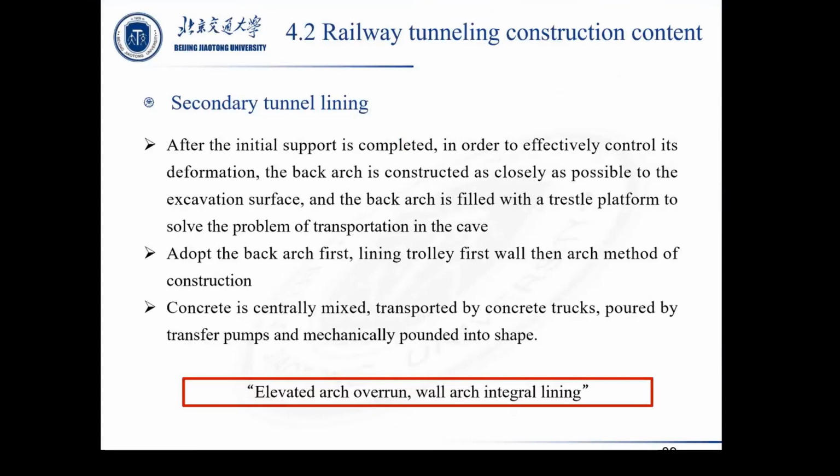And the tunnel lining should follow the principle of the invert acting ahead while the lining is done as a whole after the initial support is completed.